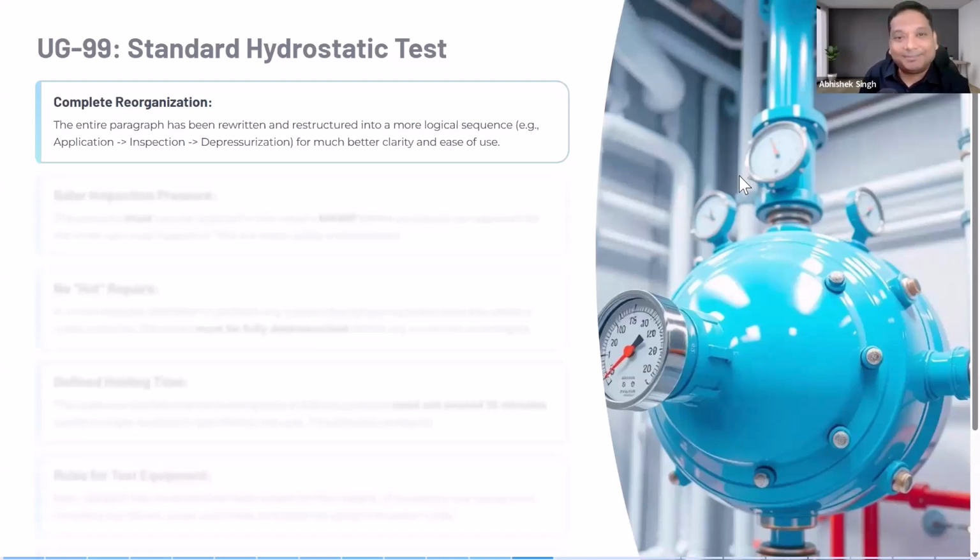So who will take care of that? The test setup has the same amount of pressure which your pressure part has. For the pressure part, you're doing all the calculation. What about the parts which have the same pressure but are part of the test setup? Nobody cared about that. But now it has been very clearly added.